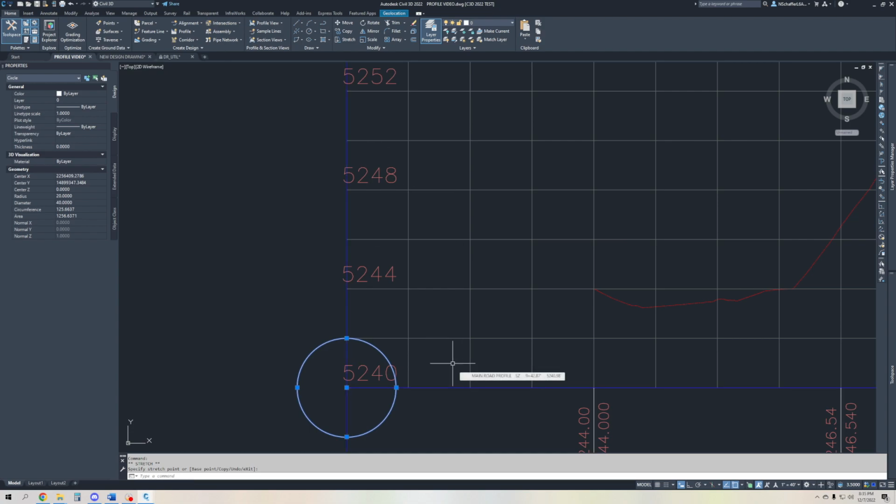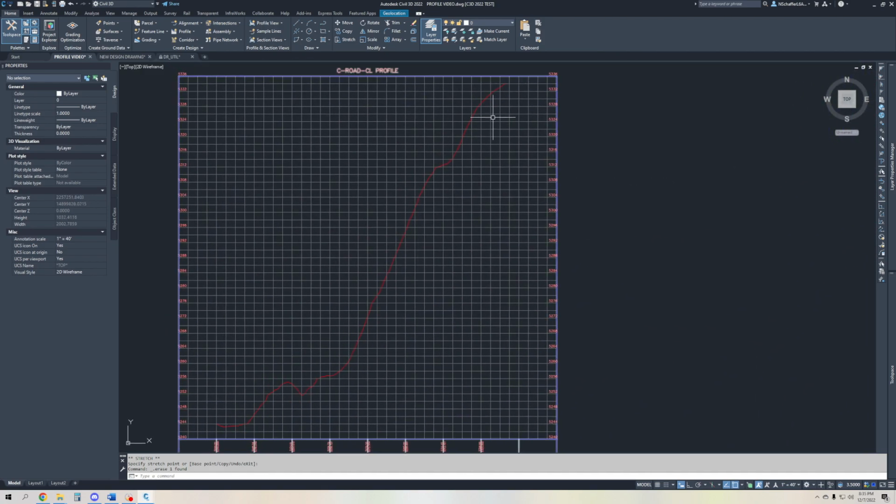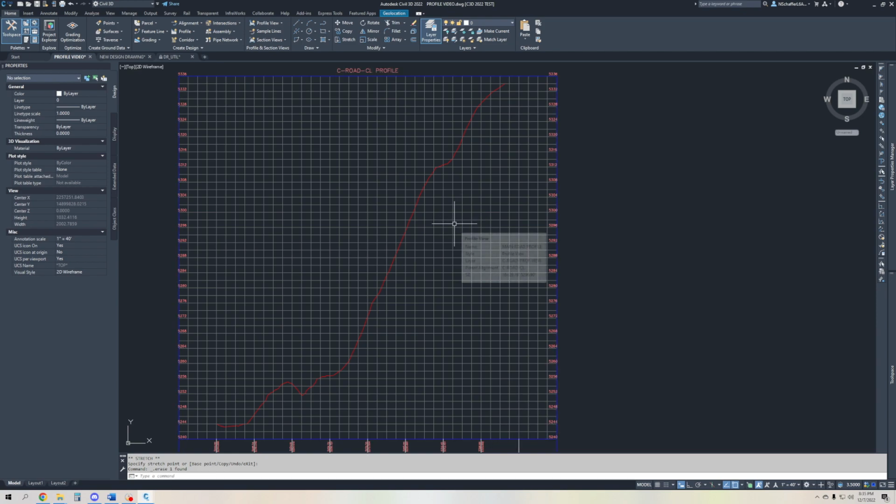It's a little bit complicated, but it's an easy way to show, if you have bends in, let's say, a water pipe, and you're trying to curve your pipe around, the exaggeration exaggerates any issues that are going on with your surface. If something doesn't look right, when you add that 10 times exaggeration, it's now going to look really bad, like you're seeing here. This looks really steep. In reality, it is steep, but it's not that bad.